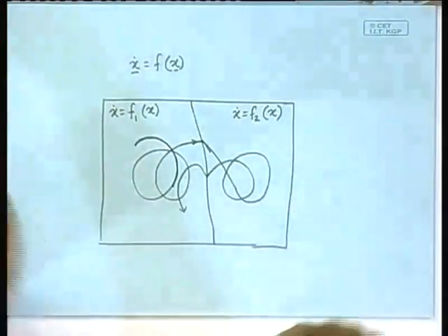If the original system is n dimensional, the switching plane can be imagined to be an n minus 1 dimensional hypersurface, so that whenever the state comes and makes contact with that hypersurface, it goes into another set of differential equations.